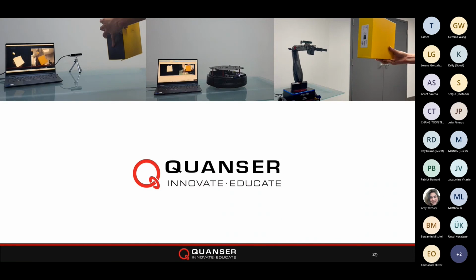Our next question is, what options are available to monitor the real-time performance of our vision applications? In addition to sample and computation time blocks we demonstrated during the webinar, you can also use the computation time blocks with a function called subsystem, which is a block in QUARC, to monitor the computation time of a specific algorithm. If you have a QUARC monitor connected to your target, you can also launch a console, which will let you know if your thread sample time is being exceeded for embedded applications.